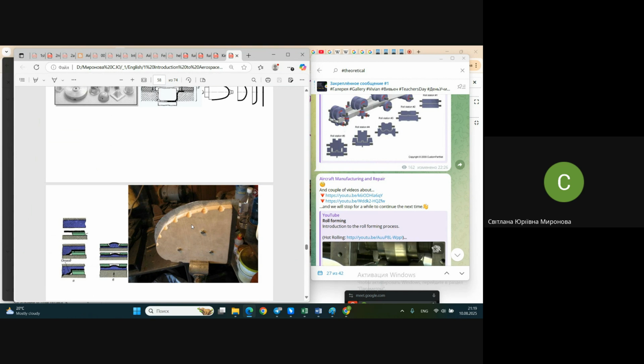Of course, it's quite clear that a metal die block is more reliable, it may stand longer work, but if you don't need some hundreds of the same part, never ever. Maybe you need to produce 50 such parts, and that is all your program. Why should you spend money on a metal die block, which is able to stand 2000? It's expensive, able to stand 2000 that you don't need. You need only 15. And in this case, of course, this stamping by rubber, as it's called, is a great thing at all.